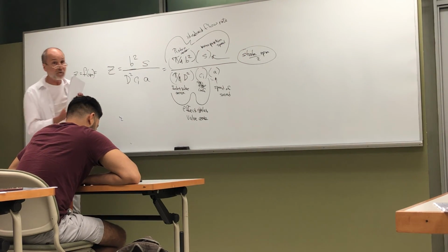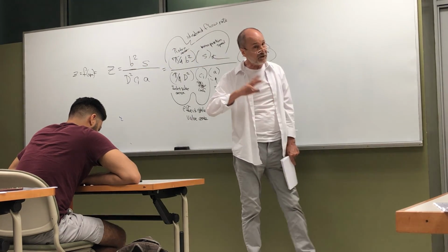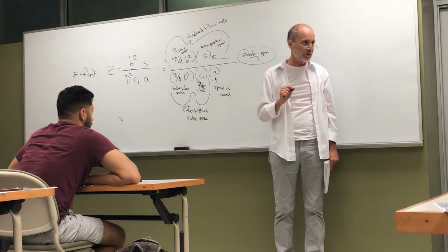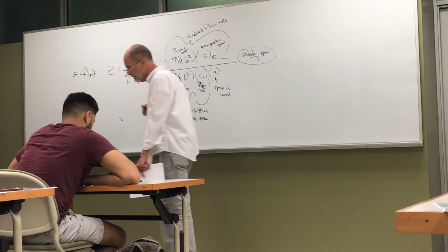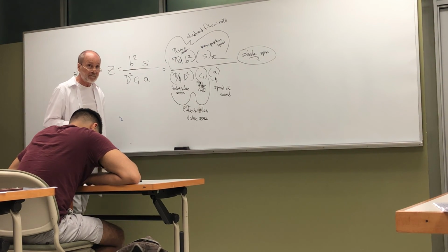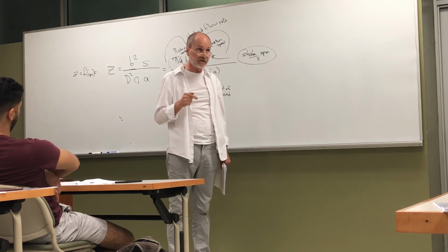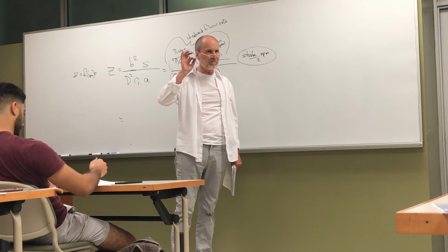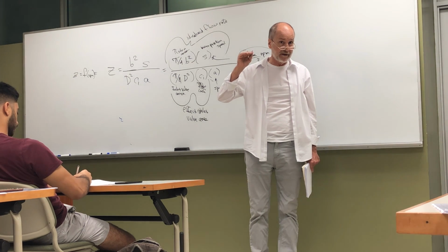So over a rather wide range, we still see when we hit Mach index 0.5 or maybe as high as 0.6, of course, this is without a tuned intake or a tuned exhaust. These are very short passages, intake and exhaust, to collect this data. The volumetric efficiency starts to drop because a greater portion of the intake stroke is undergoing sonic throttling. At Mach index 0.5, we're probably just, the peak flows have hit Mach 1.